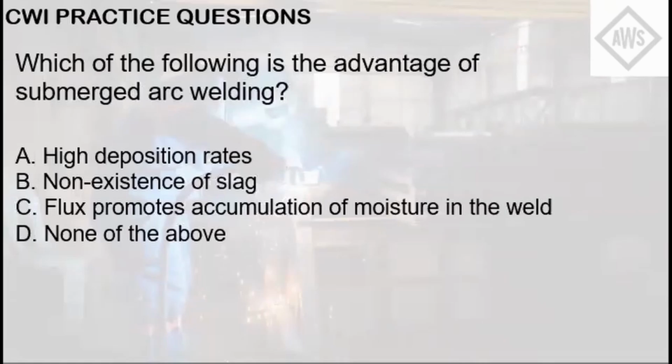If you want high deposition, you want to fill that metal in, if it's very thick, like 20-inch or even 60-inch metals. I've seen some factories that weld steel plates almost 1.5 to 2.5 inches thick with submerged arc welding.